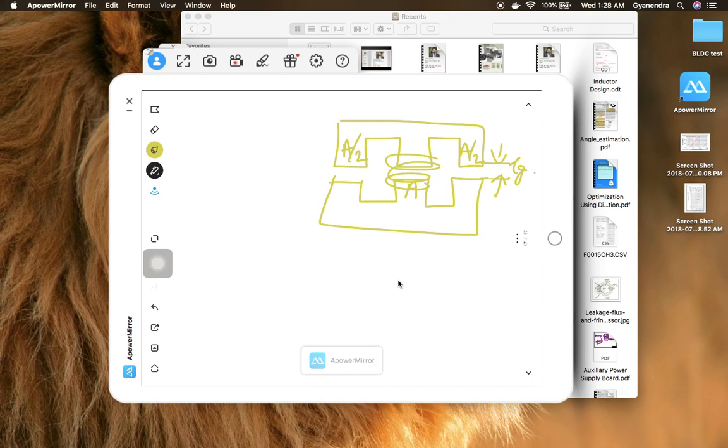So as we are going to place the winding here, let's say the reluctance of this part is R. This reluctance will be 2 times R. Why 2 times R? Because the reluctance is given by L by mu A. L is the same in all the cases. If you see, the cross-sectional area is half there, so it will become 2R.